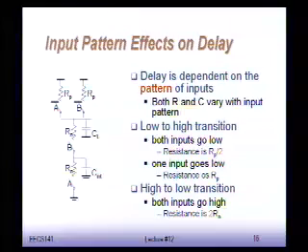So for this case, for instance, the worst case pull up has a time constant that is Rp times CL, and the worst case pull down has a time constant that is 2Rn times CL, okay? So in this case, you will try to make 2Rn equal to Rp, and in this way, you will have worst case delays equal, okay? And so this will mean that you will make your NMOS roughly the same size as your PMOS, because remember that the mobility of electrons is roughly twice the mobility of holes. Okay, so we'll go over some more examples later.